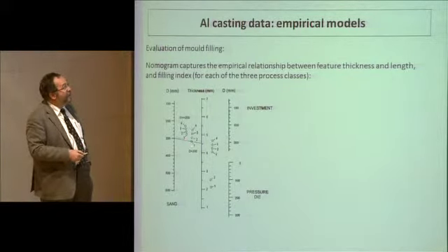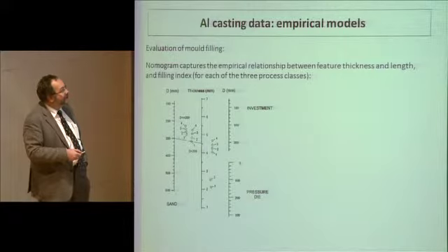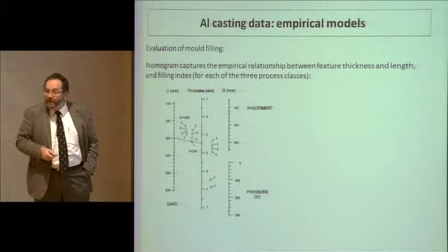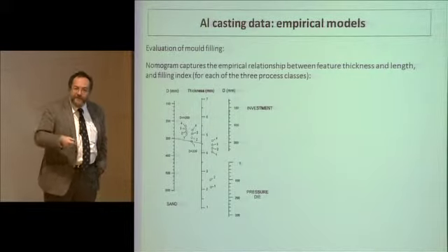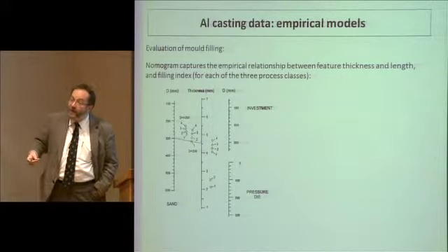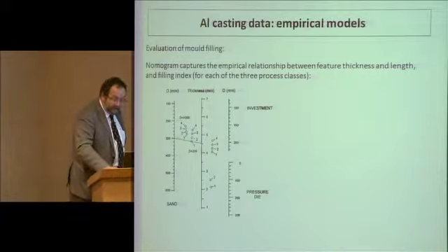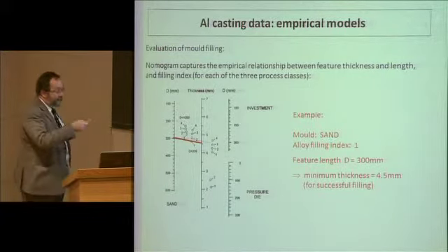When you have one where the castability index, with an index D, will tell you that with such and such a process, you can only create thicknesses that need to be higher than 4.5 millimeters. So you could probably dream of predicting that. Perhaps in the next decade it will happen. But for the time being, you just need to store this expertise.